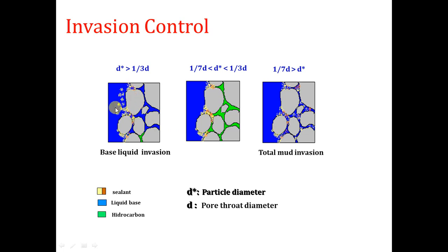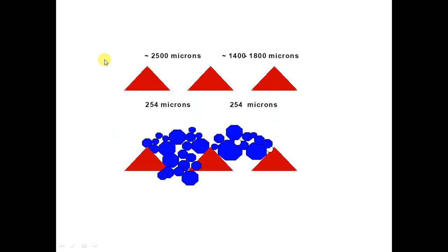So we use some chemicals or some bridging material to help us control this filtrate by controlling the particle size distribution. We are using a blend, or mixture, from different sizes, and these sizes make a very good filter cake, as you will see, inshallah, in the next lecture.